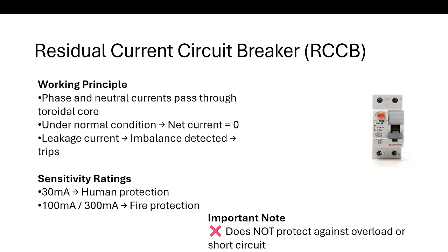There is a test button. You can see it in orange color. The test button should be pressed periodically to ensure proper operation. You have to check, and these are very important in industries.